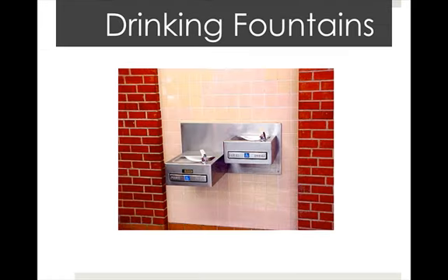Now, one last little thing to think about are the drinking fountains. These must be located outside the toilet rooms, and 1 per 75 occupants is required. And likely you're going to have one that meets ADA code.